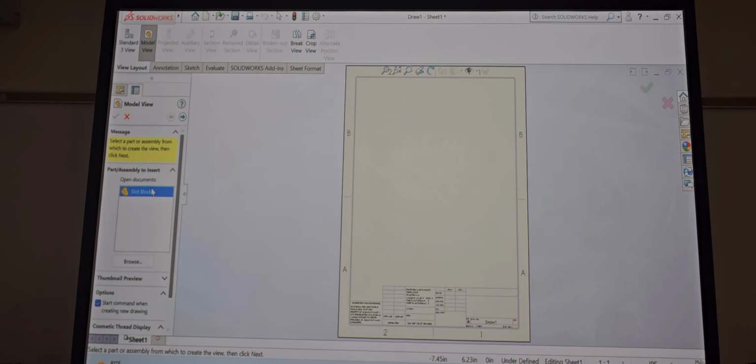Now, when you first have your drawing on the left hand side right here, that's gonna be your main one. Notice how model view is selected. So if you accidentally click something that you don't want and you gotta delete it, to get another drawing here, you gotta go back to model view. Does that make sense? I know some of you guys made that problem already. And if that happened, you just exit all the way out and went all the way back in. That's fine if you wanna do that, but you go back to model view, right?